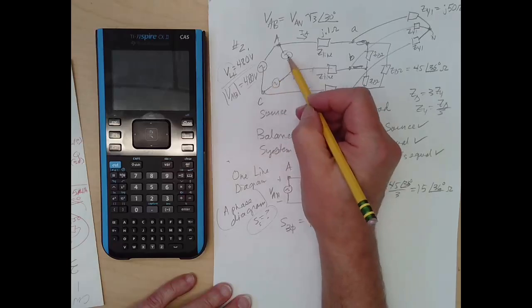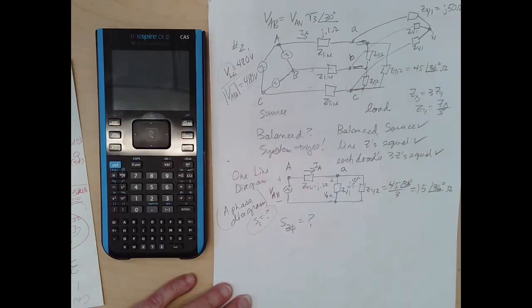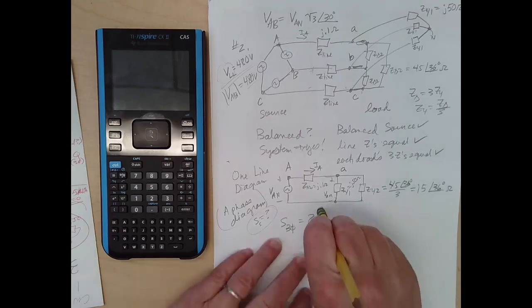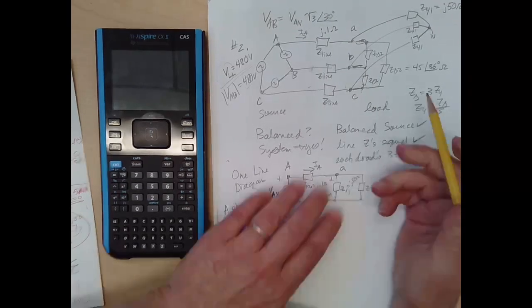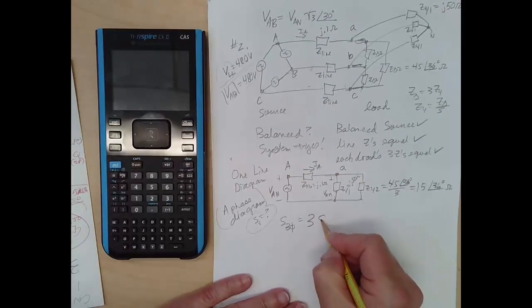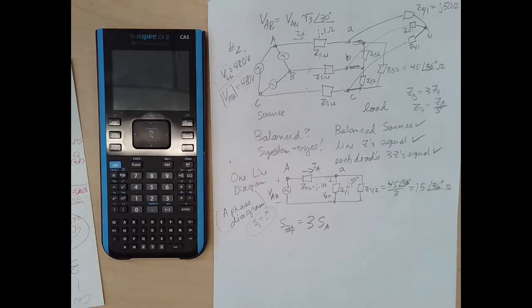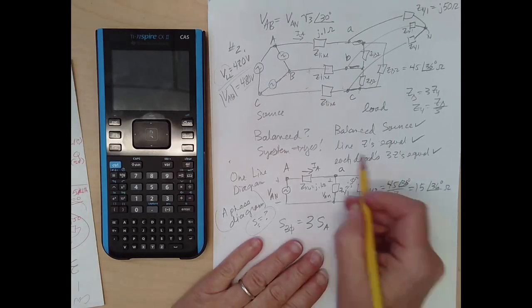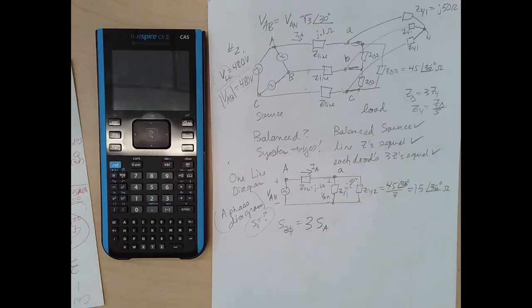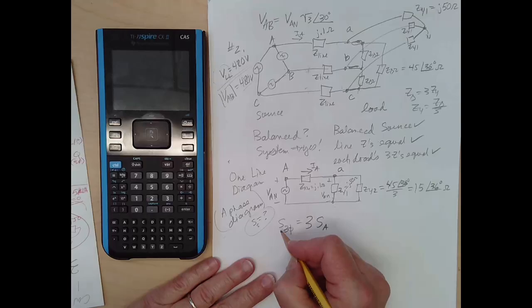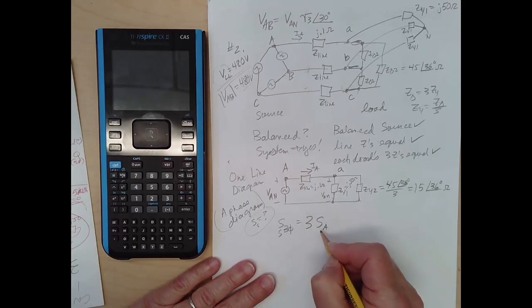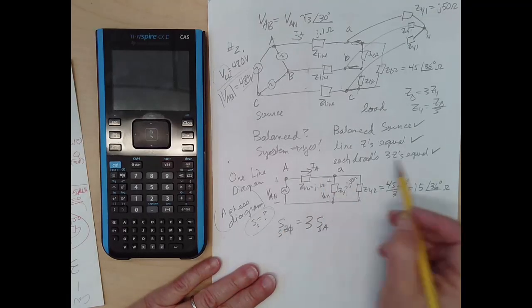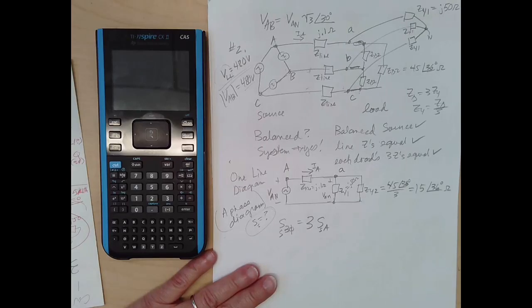It'll be the total power that all three of the voltage sources are producing, which, if we're balanced, and we love balance because it makes things easy, is just 3 times S of the A phase. This one-line diagram is the A phase, so we're just going to calculate the power of the A phase, and we can calculate power and all these different things if we wanted to.